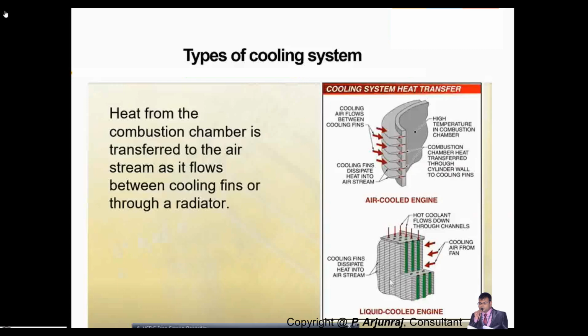So you have the fins in the form of the radiator, where the air strikes the fins. It acts as a cross flow heat exchanger. The coolant which is passing through the radiator at high temperature, when it is coming out, the temperature will get reduced because of the cold air striking the radiator.